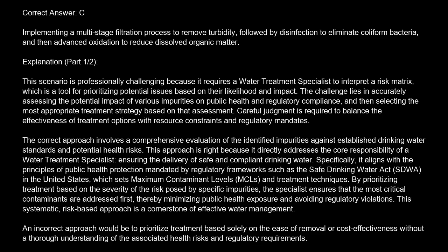The correct answer is C. Implementing a multi-stage filtration process to remove turbidity, followed by disinfection to eliminate coliform bacteria, and then advanced oxidation to reduce dissolved organic matter. Explanation: this scenario is professionally challenging because it requires a water treatment specialist to interpret a risk matrix, which is a tool for prioritizing potential issues based on their likelihood and impact. The challenge lies in accurately assessing the potential impact of various impurities on public health and regulatory compliance, and then selecting the most appropriate treatment strategy based on that assessment.